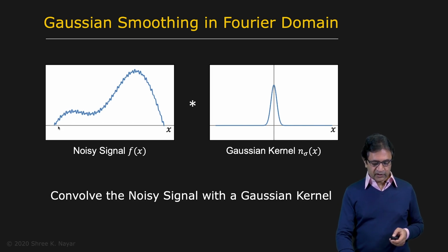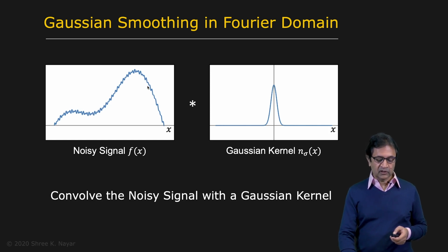So imagine you have this signal right here, and you can see that there's some noise on the signal. There's noise sitting on top of the signal that you're interested in, and you wish to remove or diminish this noise. So what you can do is you can convolve the signal in spatial domain using the Gaussian kernel or the Gaussian mask, which looks like this, with sigma x.